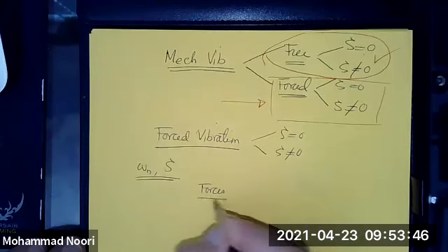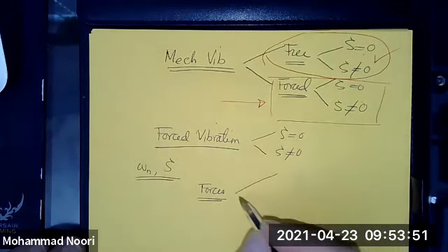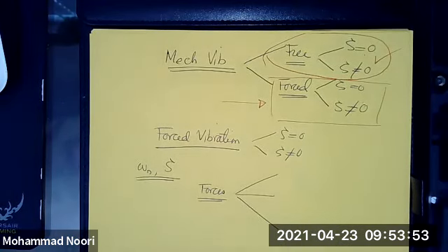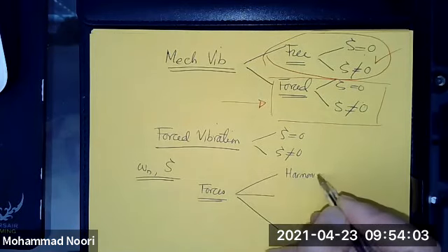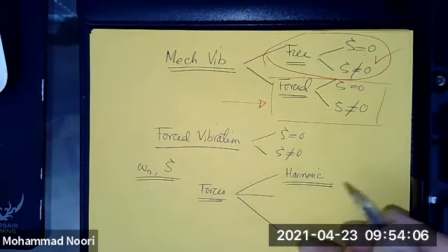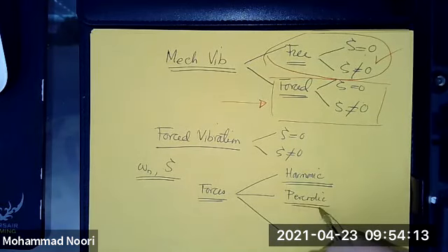So in that regard, forced vibration can be further categorized. We are going to look at a few cases of forcing functions. The most common one is harmonic excitation, when the forcing function is of a harmonic nature. We also look at the behavior of the system under a repetitive load, which is not harmonic, but it is periodic.